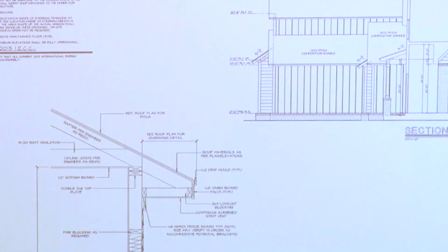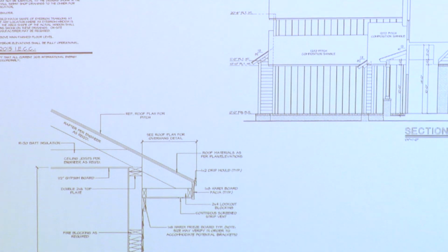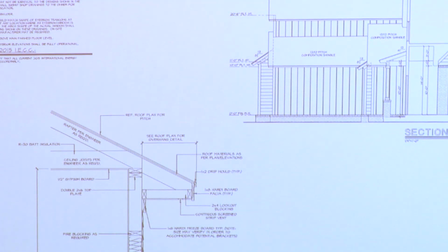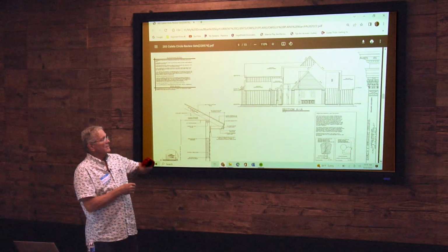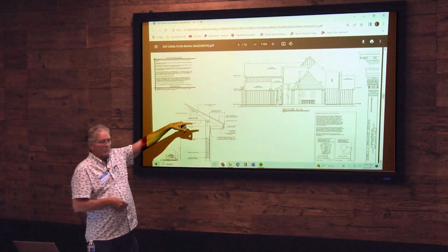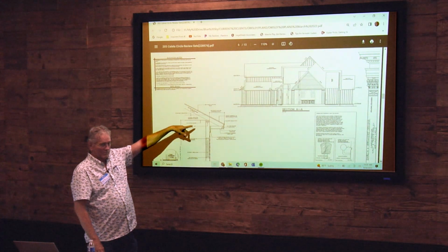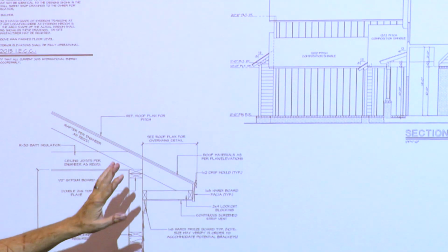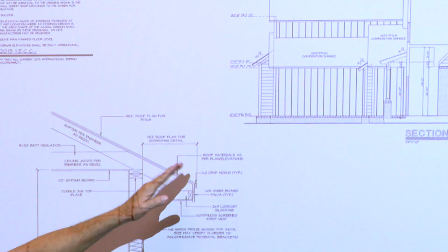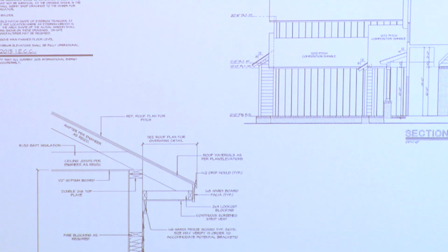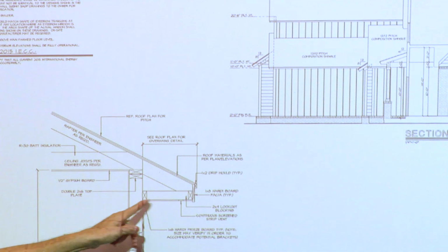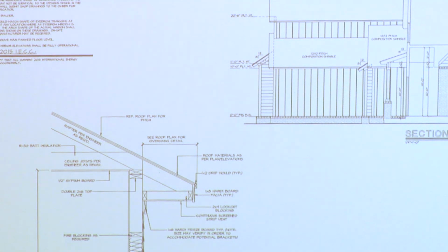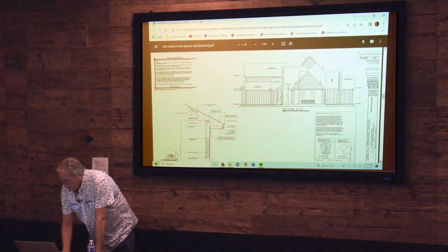And I realize all of that from my discussions with the MTO, the material takeoff worker, the estimator. He called me and said, hey, the overhangs are shown sloped, but the typical shows flat. And I said, ignore the typical. So we talked for an hour or so about how to do the material takeoff on that kind of soffit, which is a little bit different. It's not put together like this. But that's a discussion for the framing class.